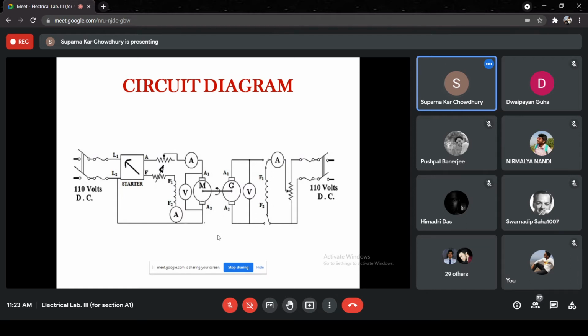If we keep the speed constant, then the motor portion of the loss can be subtracted as the motor constant loss, and the I square loss we can take care of by the current and the resistance. So under this condition, when the generator is coupled and the brushes are lifted, what are the losses? There will be losses corresponding to the motor, all the losses we have discussed. Additionally, for the generator, we will have windage and bearing friction loss, because it is rotating.